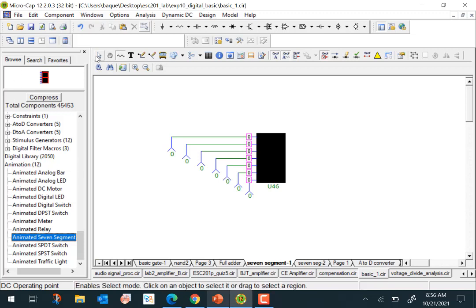All right, so I've already chosen the 7-segment display, and there are 7 segments as you will see here, and they're 7 LEDs basically, and they're driven by these 7 inputs that are there here. So for example, if I make this 1, so it makes this particular LED light up. Then I make the next one 1 here. Then this particular LED lights up. Then I make this one 1 here. So you can see here, this one lights up. So thereby we have now displayed a 7.